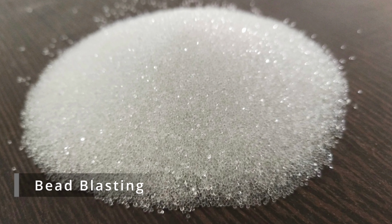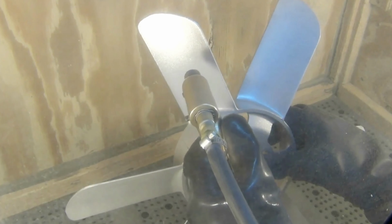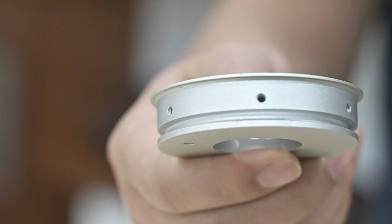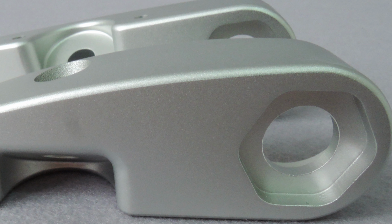Next up, bead blasting. In bead blasting, a part is blasted with small glass beads using a pressurized air gun. The impact of the particles abrades the surface, removing loose details and tool marks, ironing out imperfections, adding a uniform and textured surface finish on the machined part.